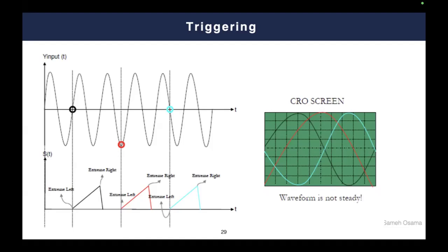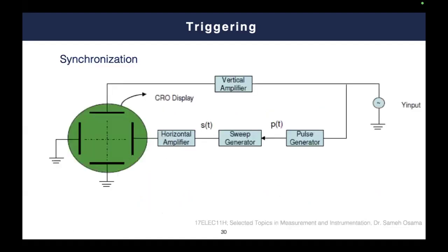self-synchronization, because again, the input is variable, so you cannot fix the triggering frequency. Definitely, if you fix the triggering frequency, you will face the problem of missynchronization because sometimes your input will not be aligned with the fixed frequency of the trigger. The result is we have to have this circuit. What is this circuit? This circuit is a self-synchronization circuit that is inserted inside the oscilloscope.